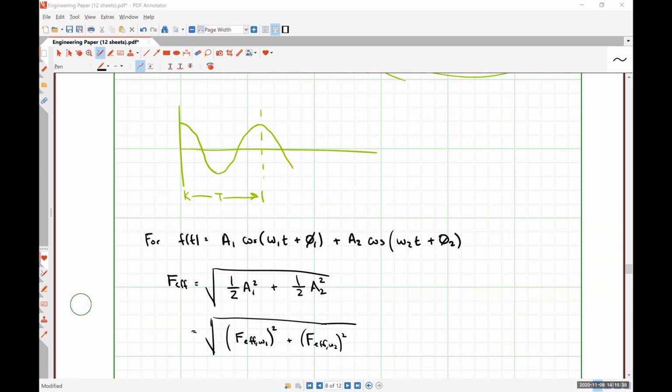That is, I'm hoping unintentionally tricky, but I want to make you aware of it because it's a really easy problem to get super frustrated on because you're doing everything right. You're just not noticing that the problem switches from phasors to RMS phasors for whatever reason smack dab in the middle of it.